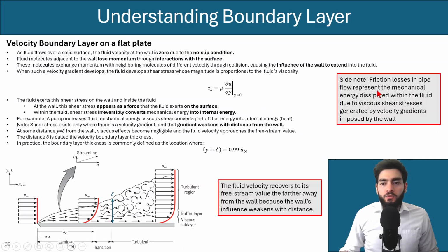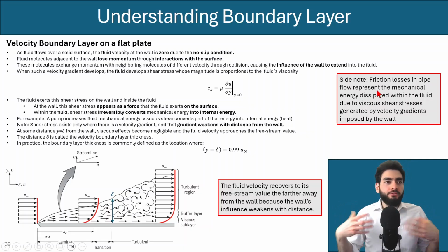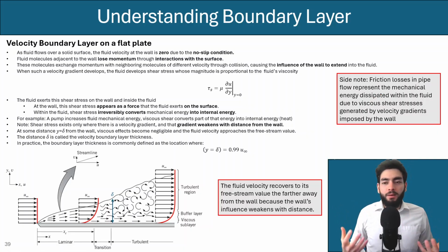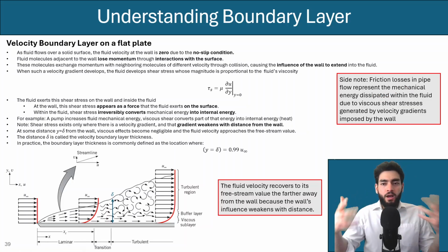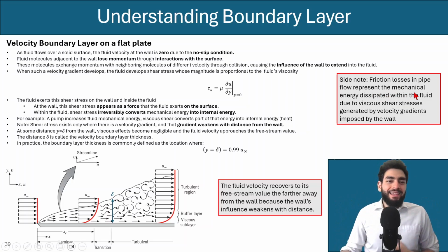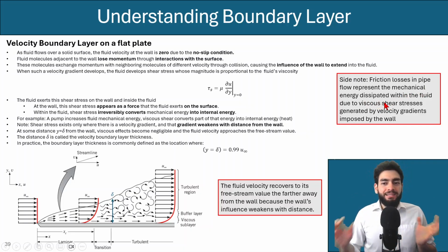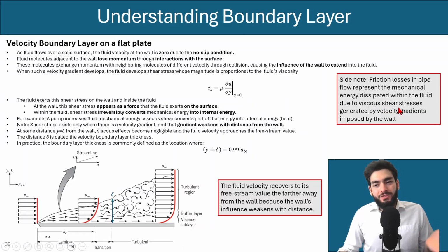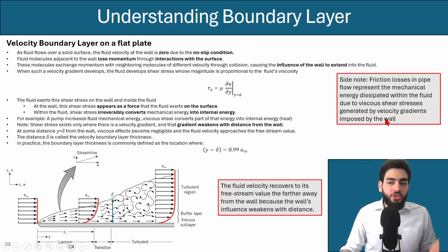Also, as a side note, this is not a fluid mechanics class and this is not a pump sizing course, but the friction losses that we use to figure out the major or minor losses in pipes essentially represent the mechanical energy dissipated within the fluid due to the viscous shear stresses generated because of the velocity gradients.